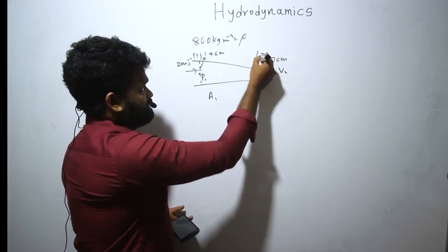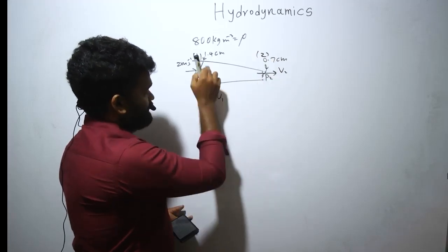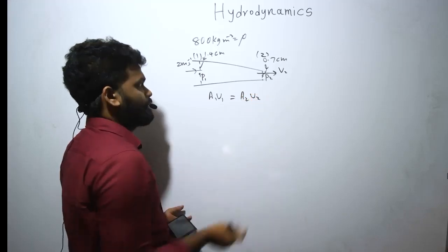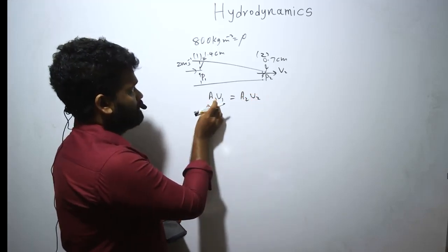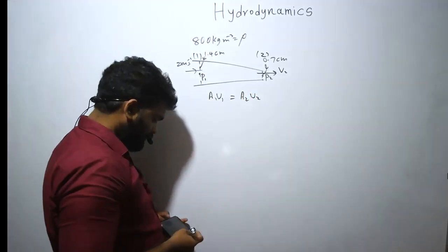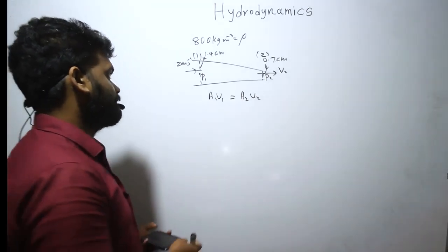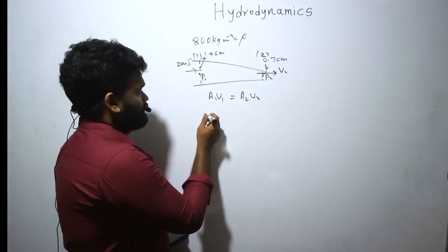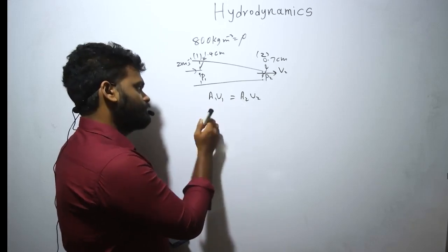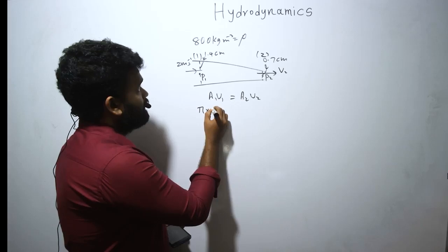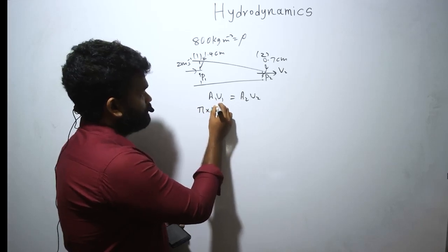The second case, so volume flow rate here is equal to volume flow rate there. So here A1. So 1.4 is the diameter, right? Yeah. Again, you don't have to convert units because it cancels off from both sides. So A1 is pi, diameter 1.4 divided by 4, squared.